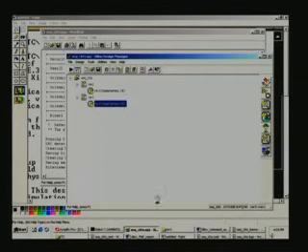So next what we will consider is the back annotation. We need to back annotate, because so far what we have done is only mapped onto a particular device, then placed and then routed it, and we need to get information for timing. For example, if you want to get delays, you need to have this what is called back annotated .v file created finally.